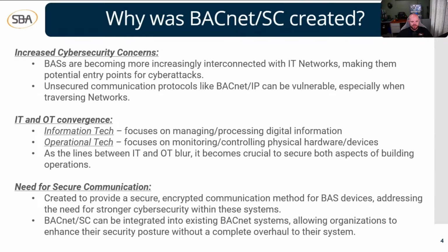And then next thing is that unsecured communication protocols like BACnet over IP can be vulnerable, especially when you're traversing different networks. So we needed something to handle all the increased cybersecurity issues that we were coming across. So then the next thing here is IT and OT convergence. If you're not familiar with what IT or OT is, I'll go over that with you real quick.